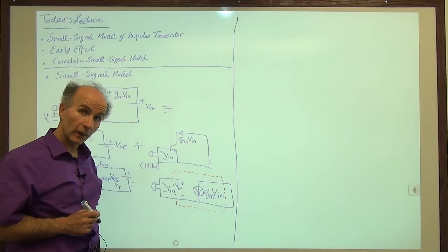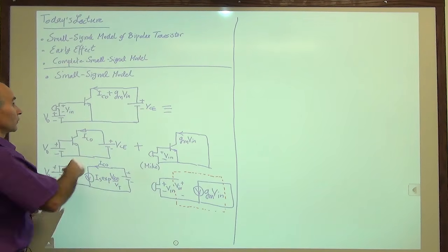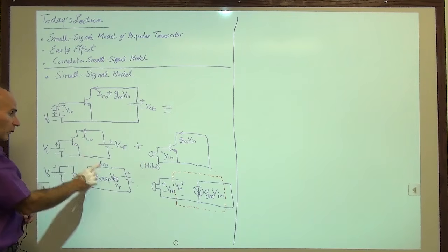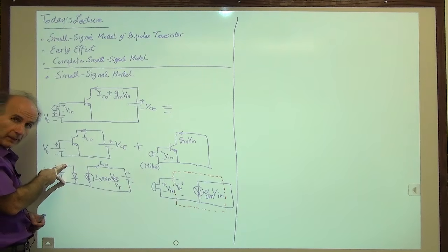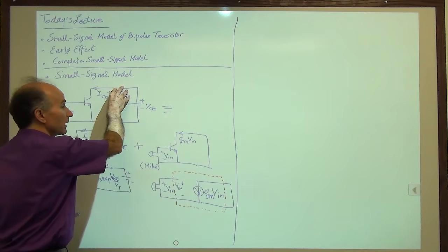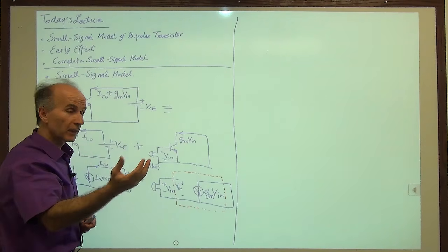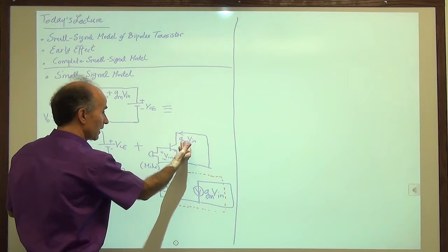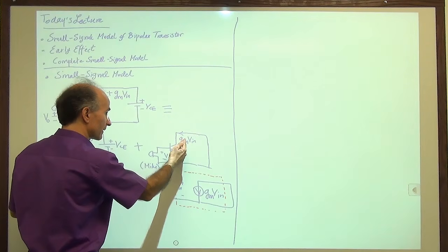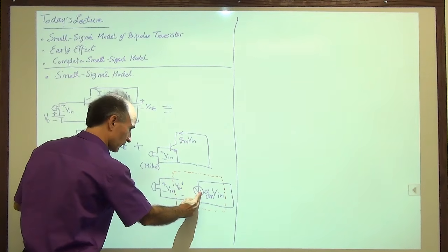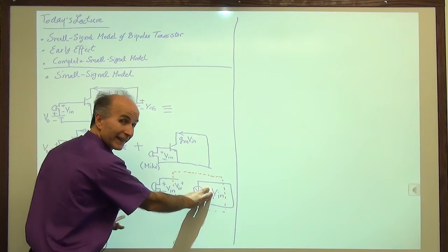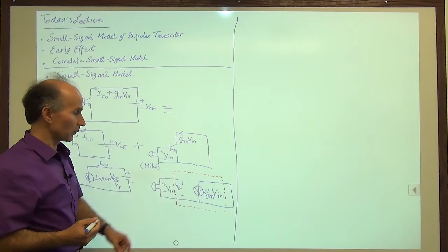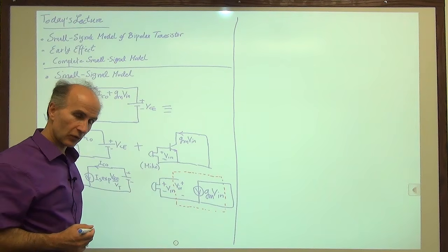Why? Well, this is because we decided to decompose this into two. One is a constant value, which has an exponential dependence on V0, and another, which is a linear term, because it's linearly proportional to Vin. And that is what we get here. This is just a current that is linearly proportional to a voltage. A current source whose value is a constant like K times Vin. So that's what we see here, which is very interesting and yet strange.